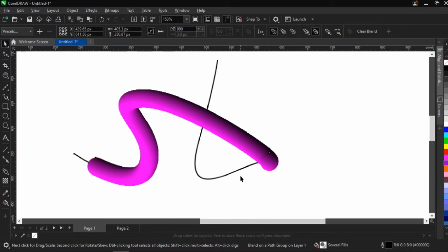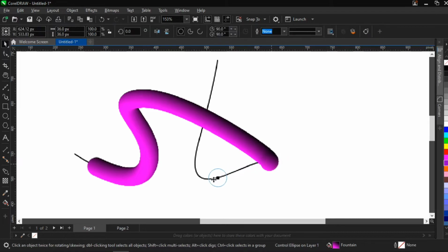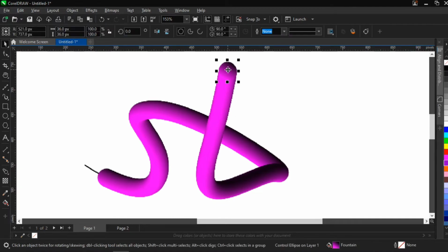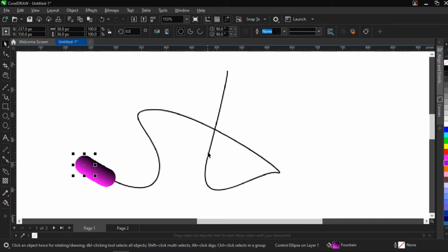The blend isn't complete. So in order for you to complete the blend, you can either choose to hold your control key, tap at this end of this blend, and you shift it this way, and this part is complete. But now there's a problem with this, in the sense that if you also take this over here to complete it here, it totally abandons this area and just fills up this area.